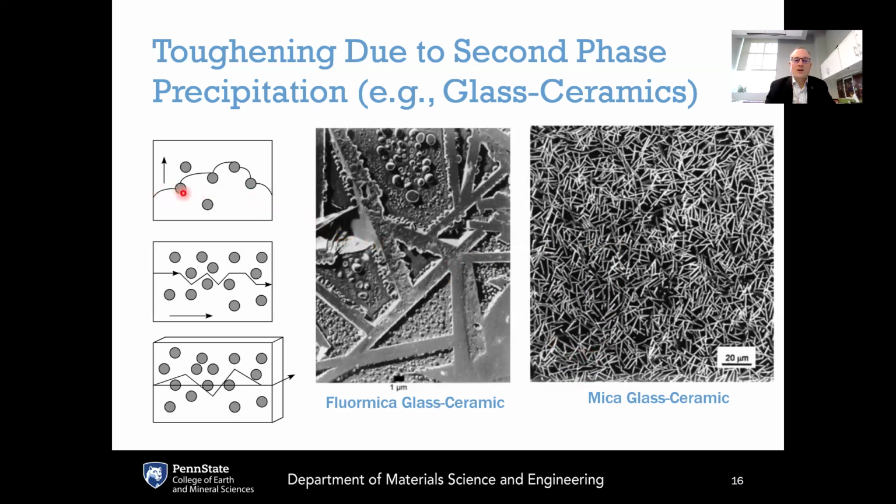There can either be crack pinning, where the crack is unable to go any further until the propagation direction changes somehow, or the crack needs to be deflected, increasing the amount of fracture area that needs to be created. So that increases the amount of fracture energy that's required to break it, or new cracks would have to be initiated at those interfaces.